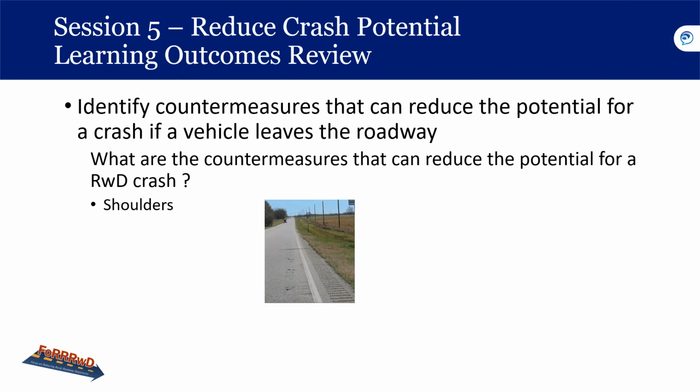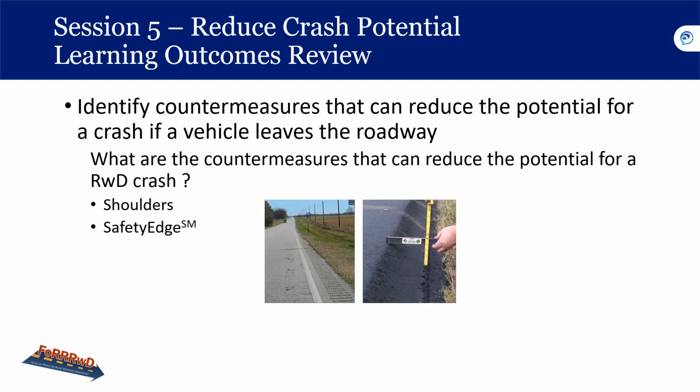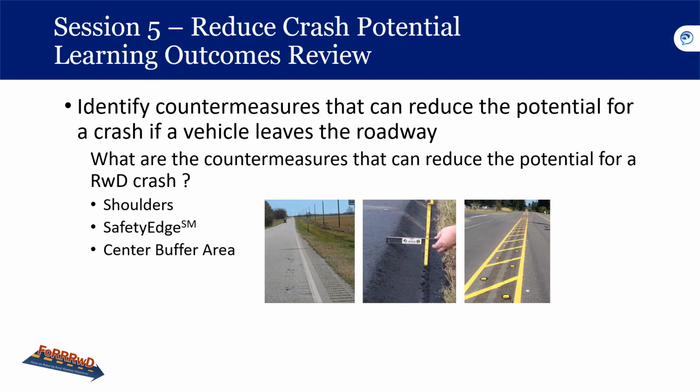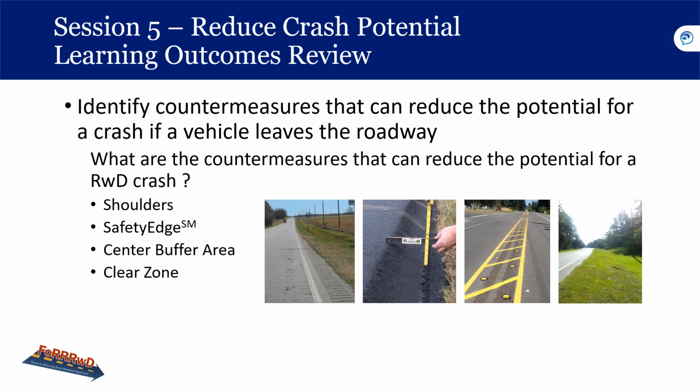So providing shoulders along the roadway, remember we talked about that. They definitely have a safety benefit. Then we have the safety edge. Another treatment was a center buffer area to cut down on the head-ons and opposite direction side swipes.